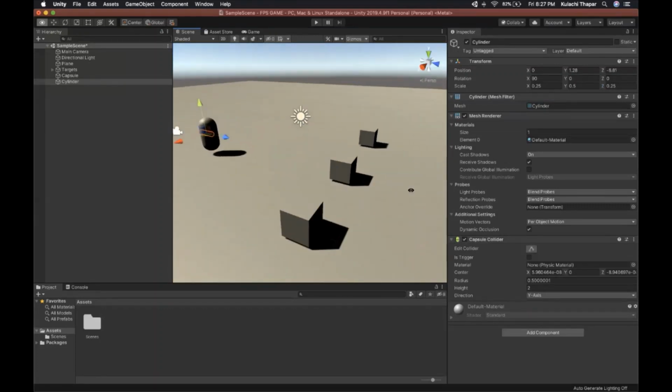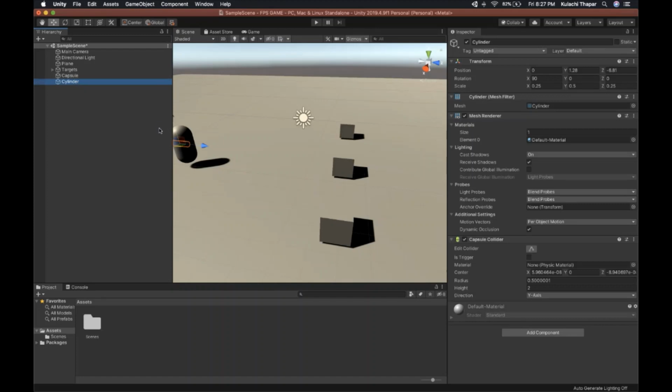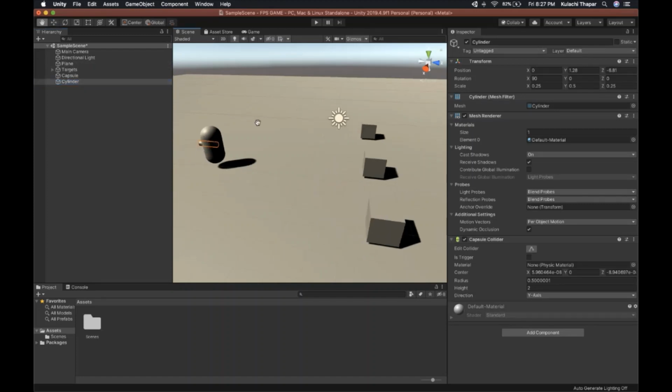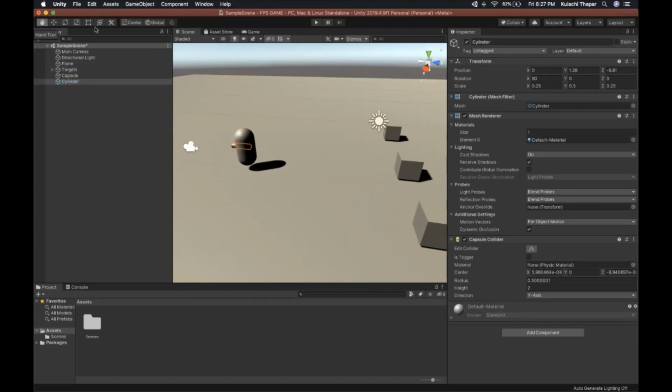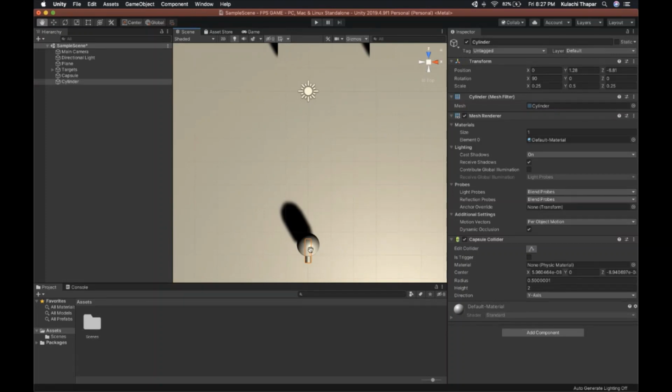Now we position it next to the player, right? And it'll take some time because it's the first time you're using Unity. One tool you can use is on the top right of the scene view, the middle one. You can see these few arrows and stuff, right? And there's a cube in between. To align stuff, if you click on this cube, it makes everything 2D. And then if you click on the y-axis, it gives you the bird's eye view of it, so you can align it without any perspective shift.